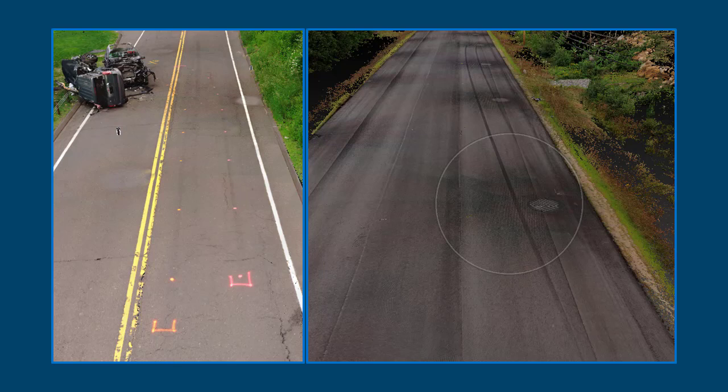And you can also see that in this case, the police agency marked those skid marks so that when they scanned it and photographed it, the location and the length of those marks are visible. Then the one on the right, the skid marks are way more conspicuous, and you can see that they go for quite a distance down the roadway. In that case, the agency didn't feel that it was necessary to mark those skid marks with paint. So it just depends on what you find. If you have a situation like the one on the left, you may want to consider putting some markers down.